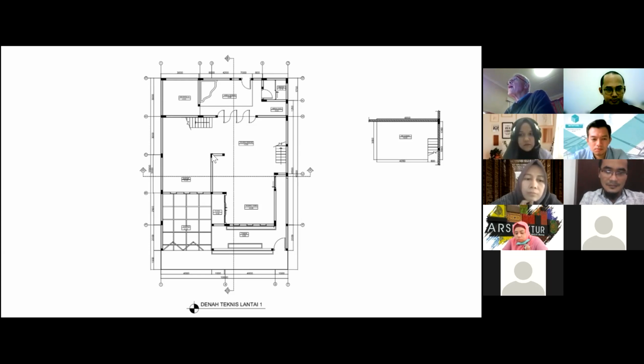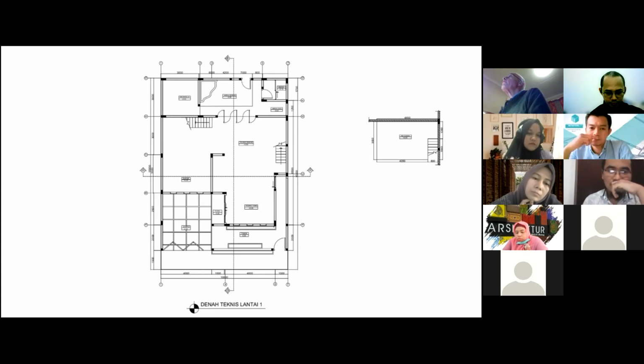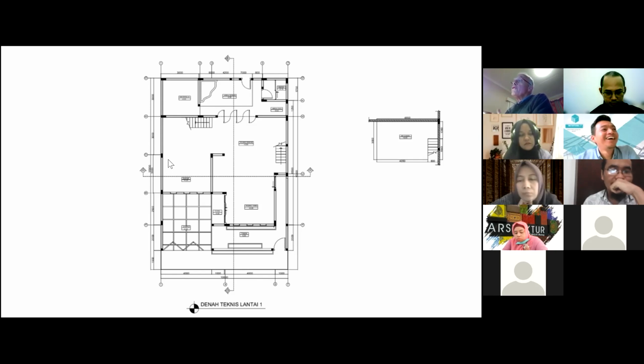Here the floor slab can span between these two walls, and the span is about 4 meters. And so for a 4 meter span, the slab needs to be about 20 centimeters. So I don't think the student has thought very carefully about how deep the slab must be for the spans that it is required to span.